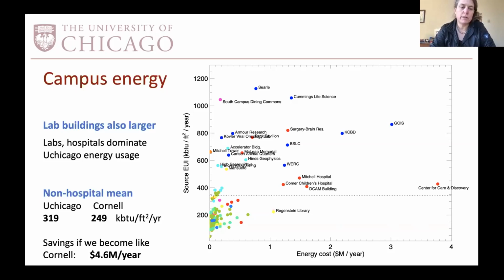Most of the energy that's used here is ventilation of these big laboratory buildings, which turn the air over in each lab multiple times an hour for safety reasons, which means you're pulling in outside air, reheating it in the winter, and recooling it in the summer, and then you dump all that air out again. So lab buildings are deliberately leaky because they have to be for safety. And that involves tremendous energy usage, and figuring out how to reduce that is probably the single best thing you could do to reduce the environmental impact of the university.